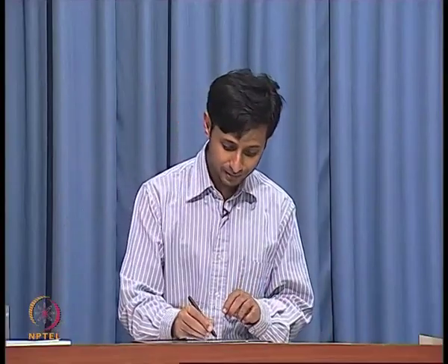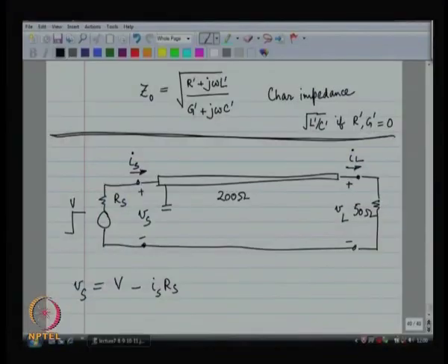All that you need to realize is that the transmission line is not a wire, there are leakage paths all over the place. So, a portion of the current can come out. So, Is is not going to be equal to Il, and that is not a violation of Kirchhoff's law. Okay.